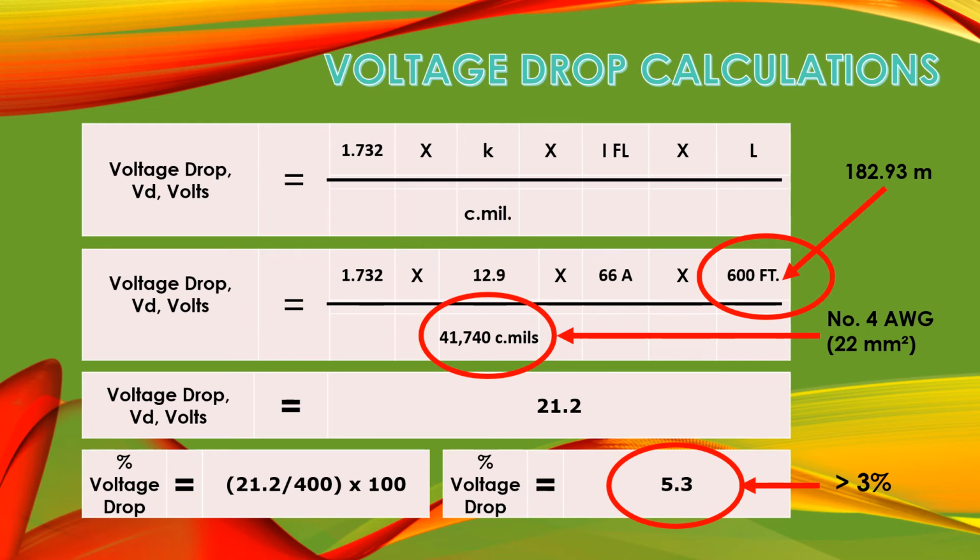Of course, it is the smaller conductor which will have the higher resistance. So here in the voltage drop calculation, we have to increase the size of the conductor to reduce the resistance. Of course, when you reduce the resistance, the current is the same, so the voltage drop will also reduce. Okay?